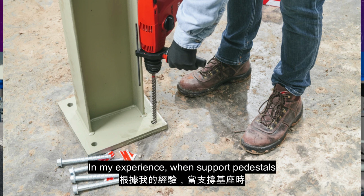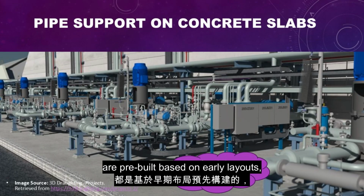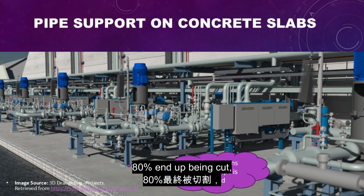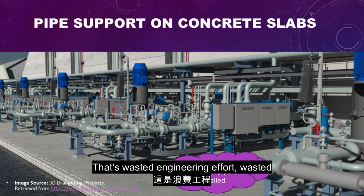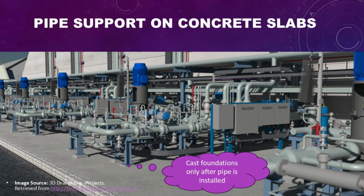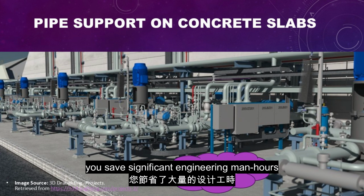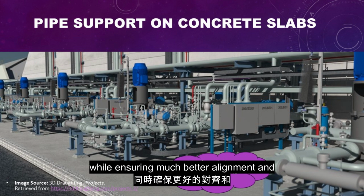In my experience, when support pedestals are pre-built based on early layouts, up to 80% end up being cut, modified, or completely demolished. That's wasted engineering effort, wasted material, and wasted labor. By delaying pedestal construction and starting with a flat slab, you save significant engineering man-hours and construction resources, while ensuring much better alignment and accuracy.